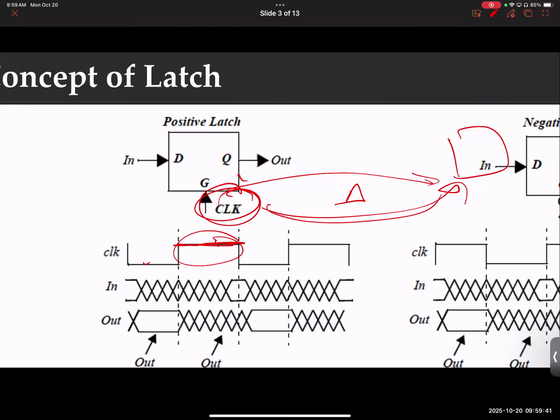Designing clock and routing clock is a very big deal in this industry, semiconductor industry. Clock tree routing is a basic design approach. So first, people design the clock route. They balance the clock. There are different ways and algorithms to design the clock. And then they design the logic around the clock. Okay, it is so critical to make sure the delays are balanced. It's not an easy thing to do. That's why it's so tough to speed up microelectronics.